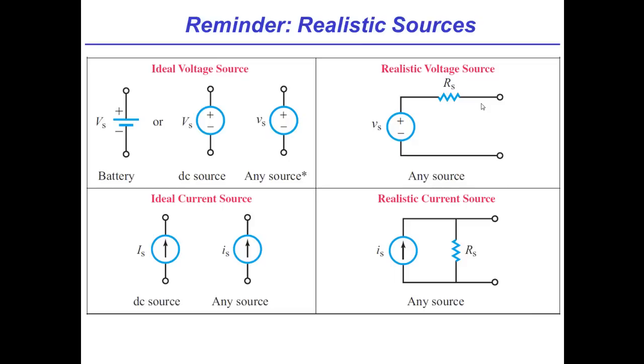Okay. So why does that voltage go down? It goes down because there's a series resistance associated with that battery. When you pull more current... Oh, I see. You're saying, let me see if I understand. You're saying that there's effectively a resistor here. And so when you pull some current, the actual voltage on this is going to change from the base voltage? Is that what you're saying? Correct. What's going to happen is we have a load sitting over here, which let's model as a resistor for now. Okay. So we have a load sitting over here, and the normal load is the load of the headlight, and so there's a certain voltage that appears across the headlight because this is a resistive divider. Right.